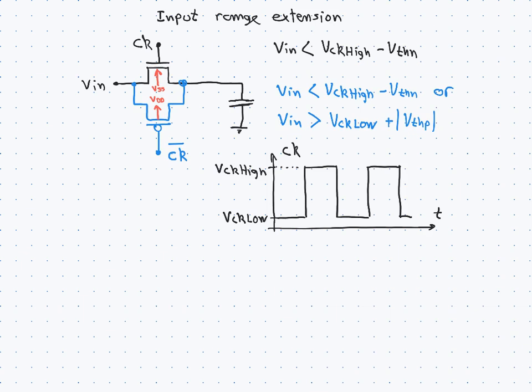Also, during the sampling process, the source can actually change. If, for instance, the sample voltage is lower than the input voltage when the transistor turns on, then the N transistor source will be on the right hand side. If, on the other hand, the sample voltage before the transistor opens is higher than the input voltage, then the source will be on the left hand side.